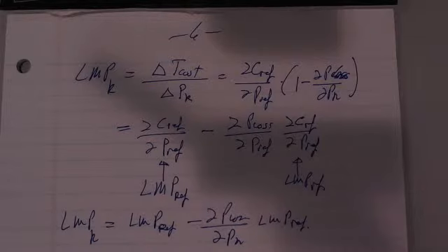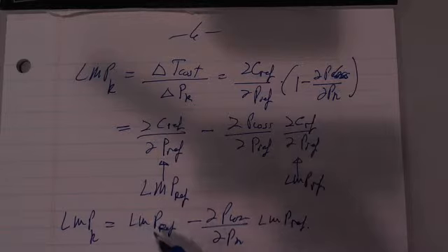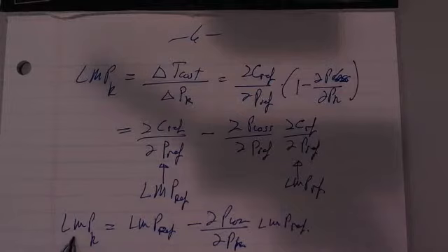It says that whatever the cost at the reference bus, assuming it's a generator, which you normally would have it as, if you take the derivative of losses out at bus K, dP loss dPk, that incremental loss times the same thing gives you the LMP at K.